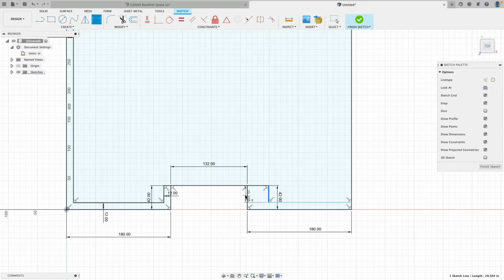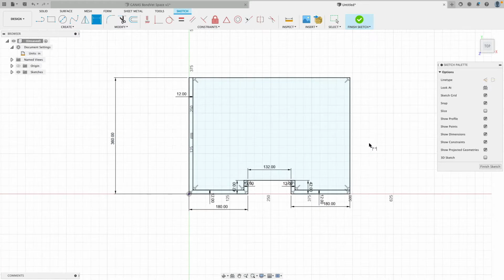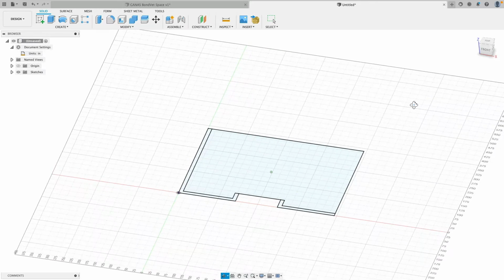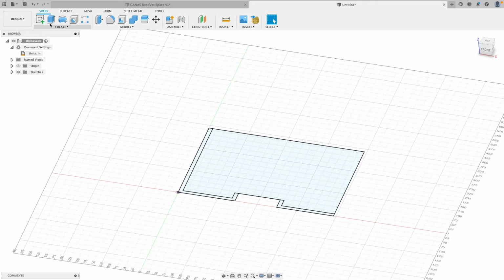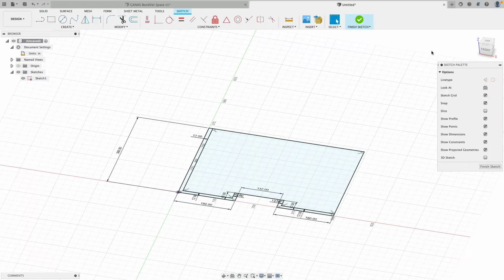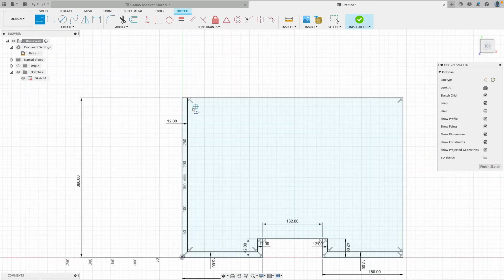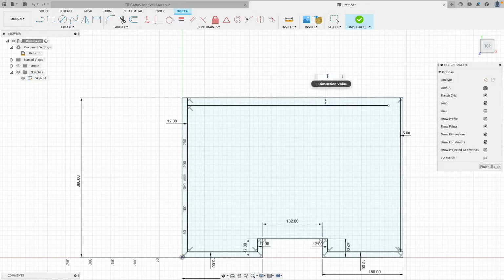Okay, very good. 12 inches, and here we do a dimension 12 inches. Cool. Okay. Now we have actually kind of like the basic down. We can at this point continue adding a little bit more information in. So I will have here later an interior wall, and I will also have here an interior wall. The interior wall we specify with 5 inches material thickness, wall thickness.